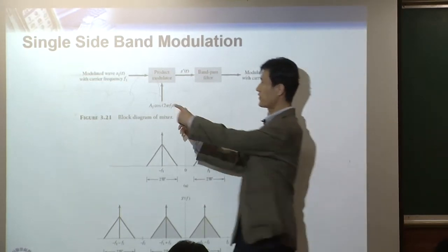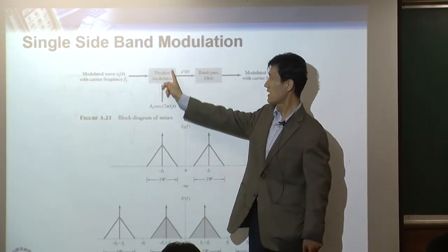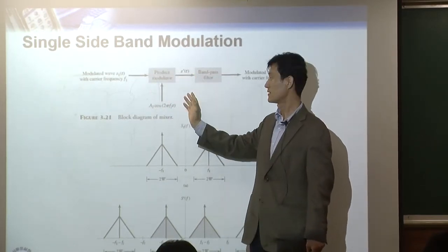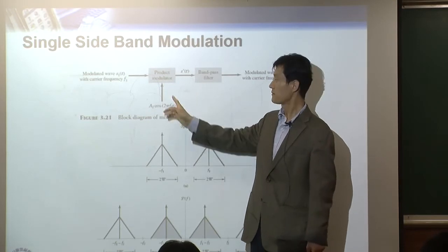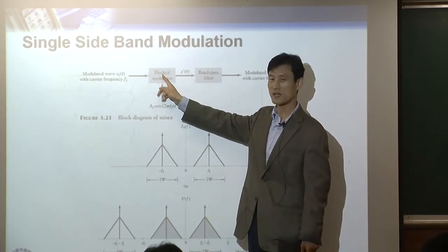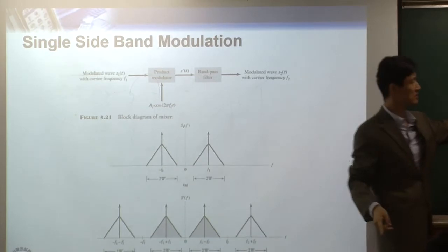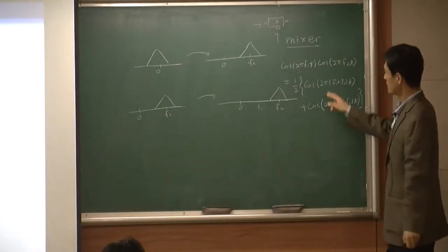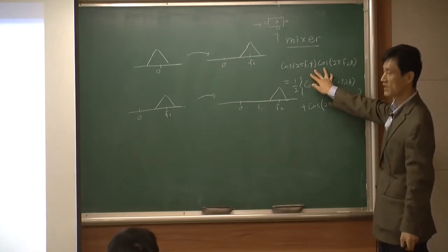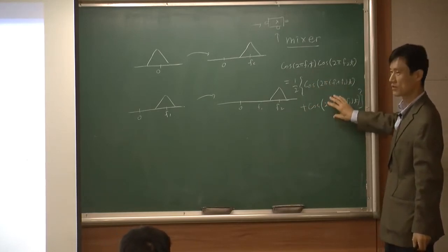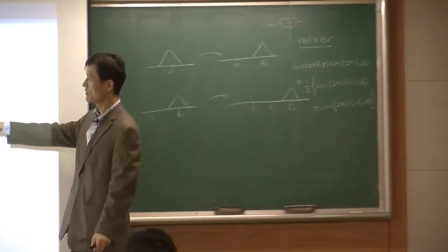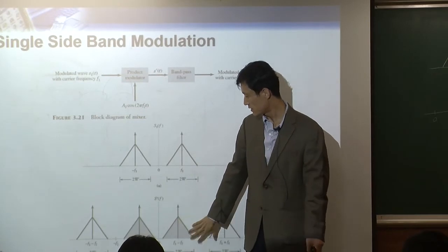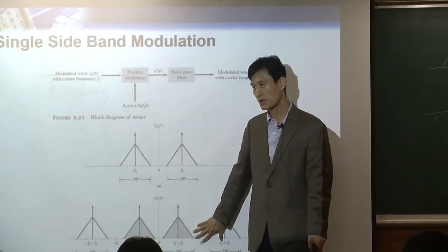So when you're mixing two different frequencies, what happens inside of the mixer? The whole thing is a mixer, hardware. What is inside here is simply you multiplying two different cosines, like this. Then, since we already know the identity, you change this multiplication of two cosines into addition of two cosines. That's what happened here. So the output S prime t looks like this in frequency domain.